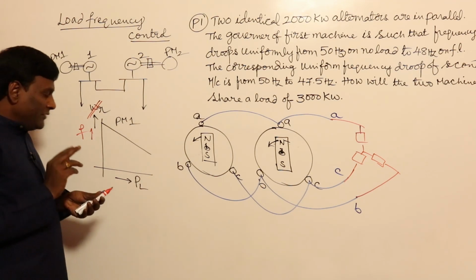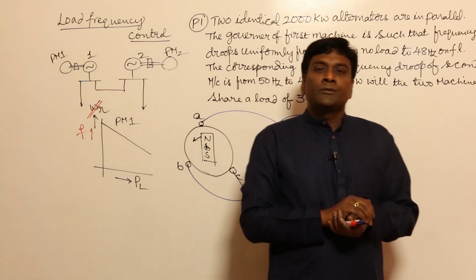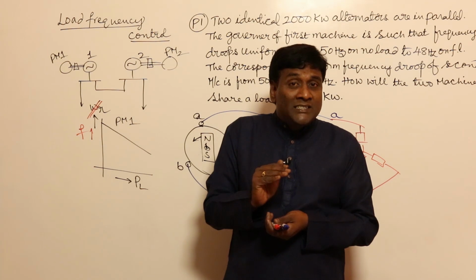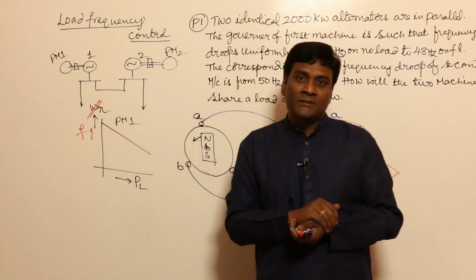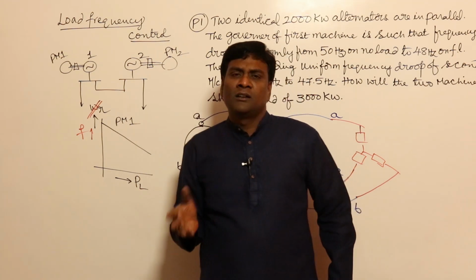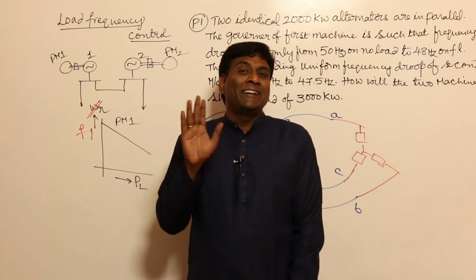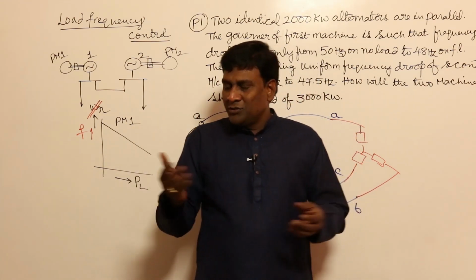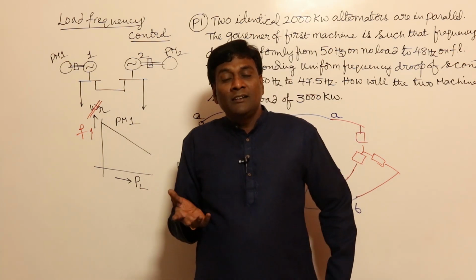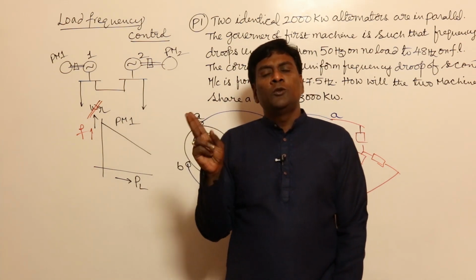Now if I think of synchronous machines, basically two machines connected in parallel will be there, or one machine connected with an infinite bus. Let me repeat again multiple times: in stability we analyze the same, and in faults also we analyze the same. So it's two alternators, not like a transformer, not like DC generators. Even in a few videos I have seen people connecting 10 alternators, 5 alternators for parallel operation. No, only 2 alternators will be there.